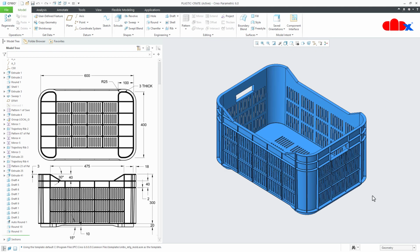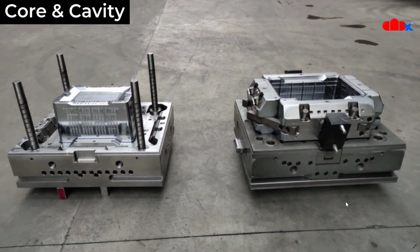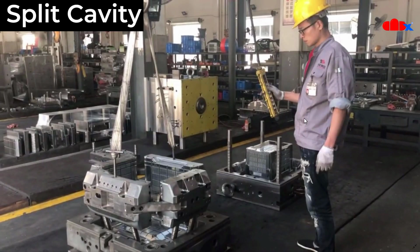So once your design is over, this is the first phase. The second phase is the mold design based on this part reference, and this mold will look like this. So this mold includes the core assembly and the cavity assembly. So this is the core and this is the cavity. Now this cavity is a split type cavity. So if you see next slide, here you can see this is the core and this is the cavity. It is split into multiple pieces.